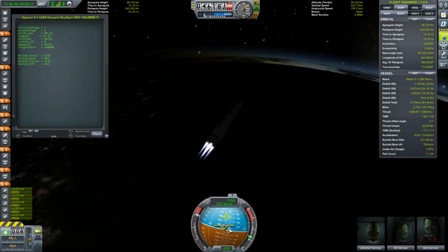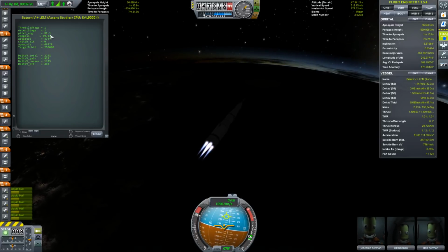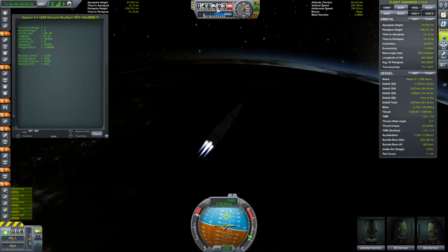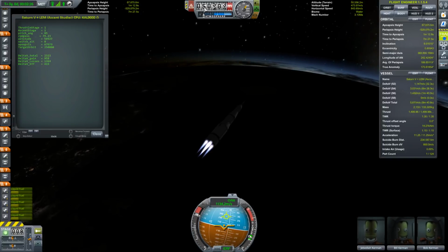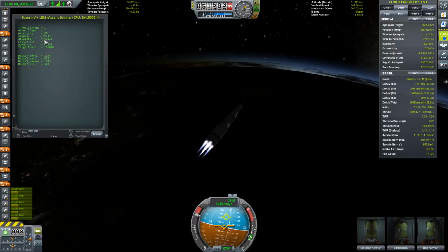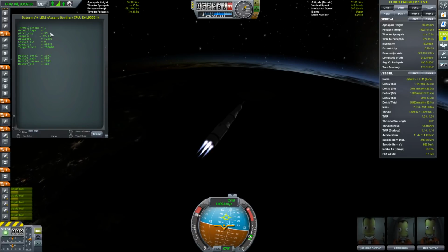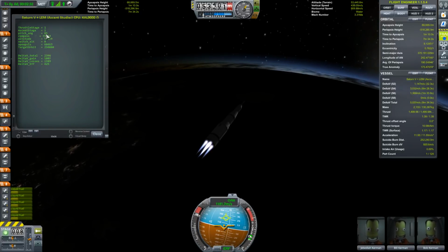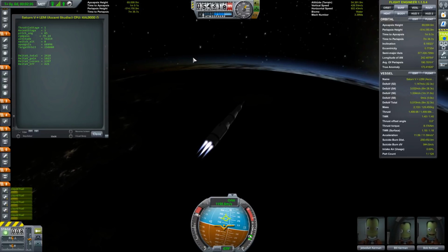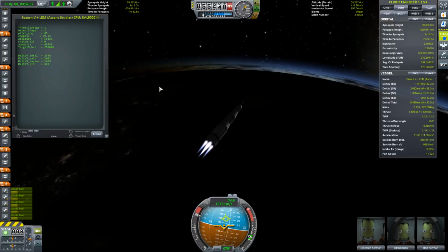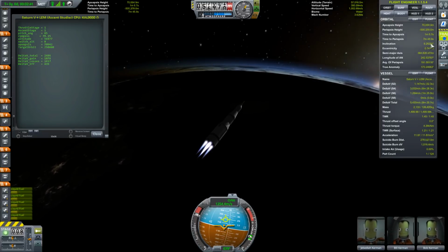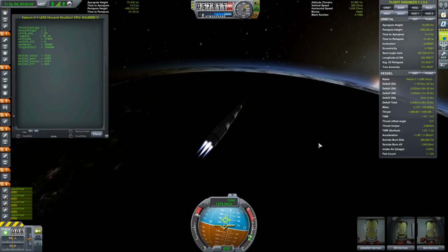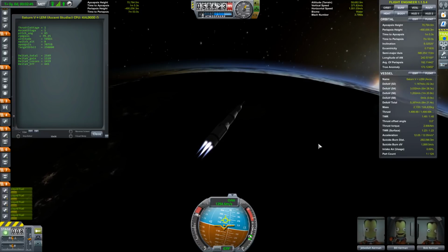And by the way, we're about to hit that 5 degrees here, and you can see that we're getting pretty close to 49 kilometers. Boom, 85 degrees, 49 kilometers. So that's what I wanted to do, right? I wanted to pitch over at 85 degrees, or 5 degrees pitched up, when we hit that 49 kilometers. So that worked out pretty well. And you can actually see the inclination starting to taper off because the velocities start to align, and so the difference isn't very big, but